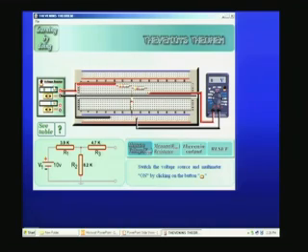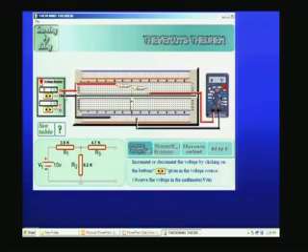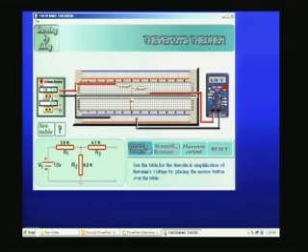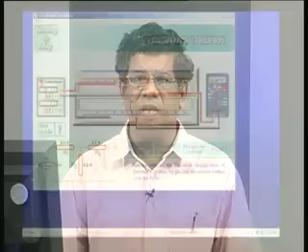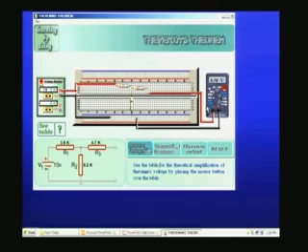Now I will have to measure the voltage using the voltmeter. Before that I should switch on the power supply. So switch on the power supply, switch on the multimeter. Now start applying voltage by using these increase buttons. I will apply, let us say 10 volts, because that is what we started with. So I apply now 10 volts for this circuit and measure the voltage across the load terminal after removing the load, and you can see the voltage on the multimeter is 6.78, which is what we calculated in the previous slides. So measuring the Thevenin's voltage is very simple. Just remove the load, connect a voltmeter, switch on the power supply and measure. You find it is 6.78.